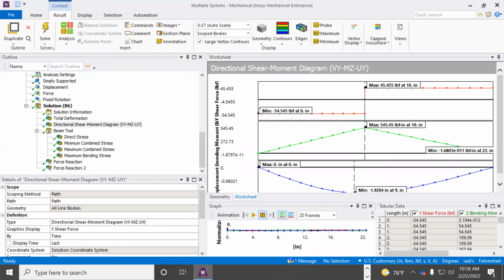I'm getting here the shear force going downwards instead of upwards, but it is what we expect for a shear diagram. Look at the moment here. I'm getting the maximum moment I expect. And look at this blue curve. This is my elastic curve, or displacement function.